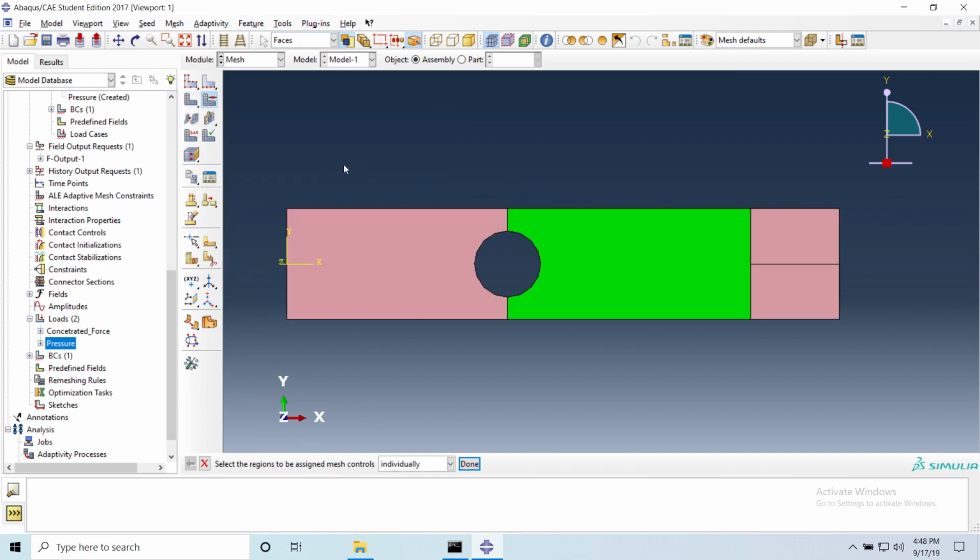And then sometimes for cracks, you need a good refinement near the crack because you want your stresses to be super accurate. So the more nodes you have, the better your solution is gonna be, but the more computational resources you're gonna need. So you have to decide how many nodes you want, but also how much time you want to spend running this simulation.